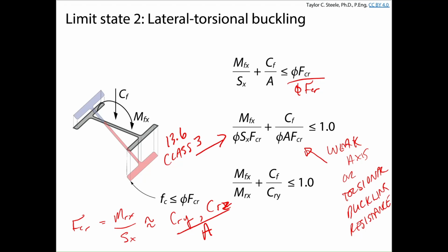So these are all very similar. The other day, tension made strength worse. Today, compression makes strength worse. On Monday, tension made lateral torsional buckling better. Today, compression makes lateral torsional buckling worse. The same limit states, just checked slightly differently.